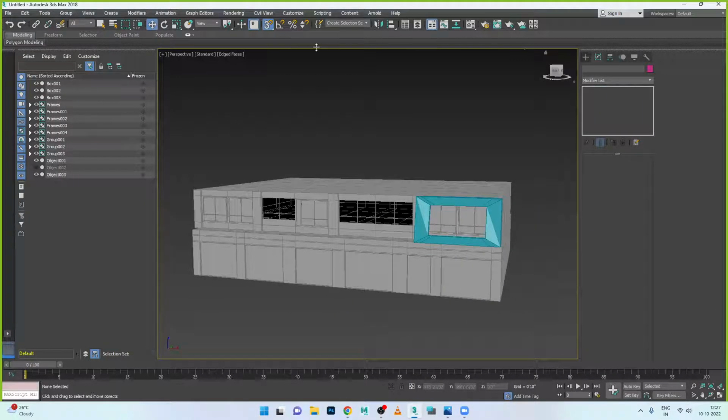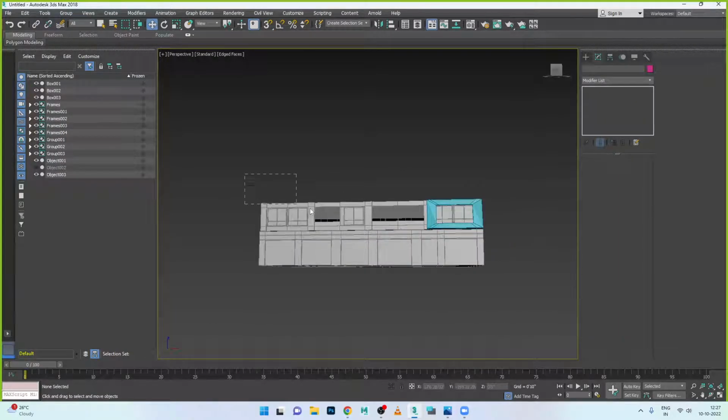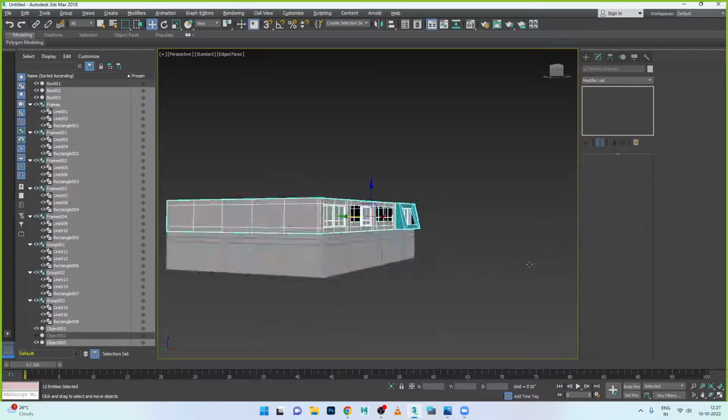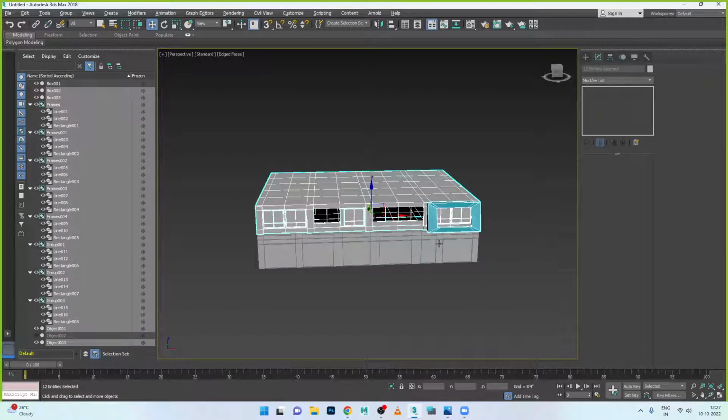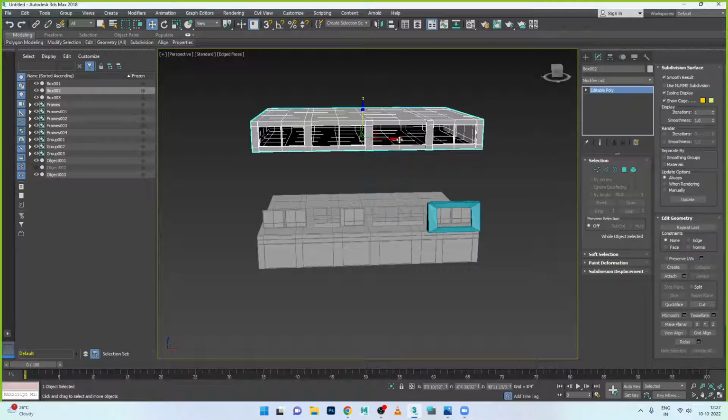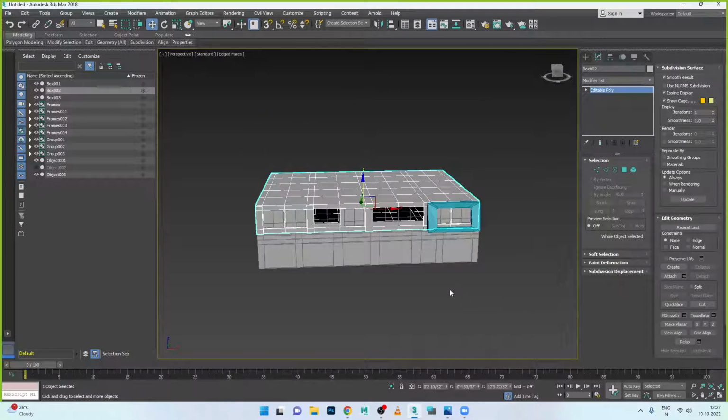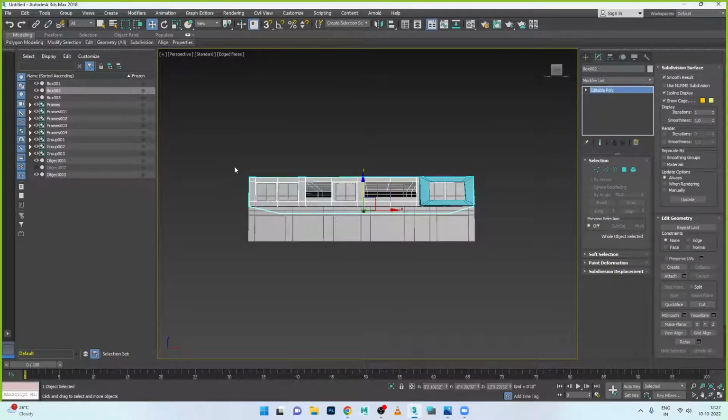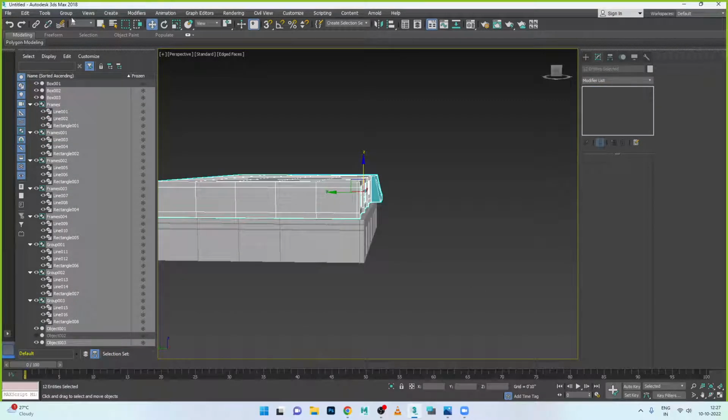Now what we need is the same block should come as multiple pieces. So what to do for this one: make selection of this complete block, select it, and then group it now. Okay, Control G to group, and just see whether it is moving all at a time or not. See, it did not group. Why? Because we have just selected and have not created the group on this one. Select all this and group it. So name it as floor, we can say.